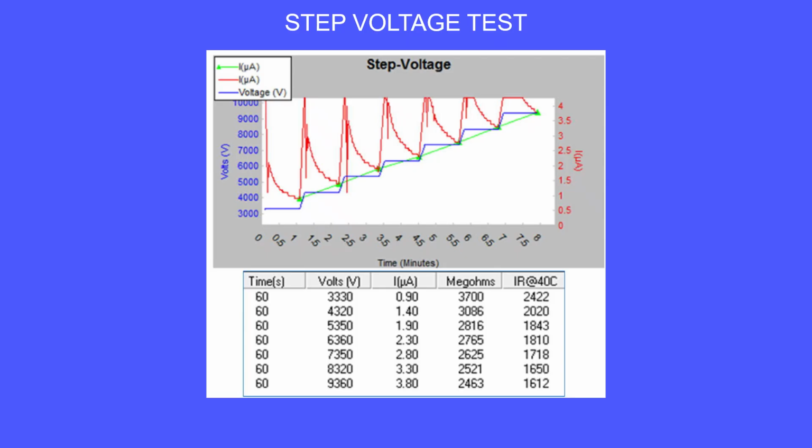As this test is performed, the person performing the test should calculate the difference between each step and make sure the difference is not increasing. Differences here are 0.5, 0.5, 0.4, 0.5, 0.5, and 0.5. This is an excellent result.